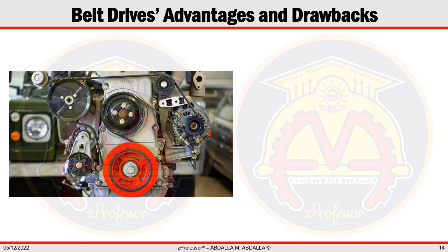Although a belt may slide when it becomes overloaded, it offers some protection for the driver and the machinery it drives. Belt drives also provide the benefits of easy operation, straightforward design, and shock absorption. Their application frequently streamlines machine design and significantly lowers manufacturing and maintenance costs.